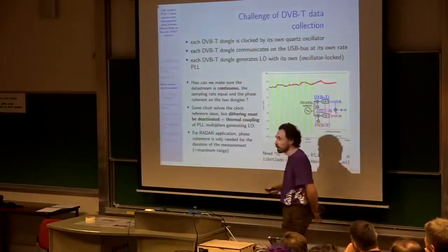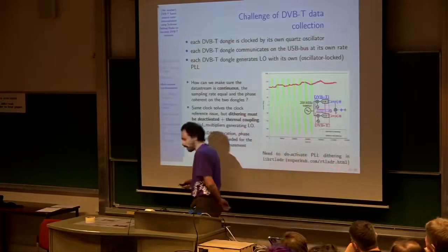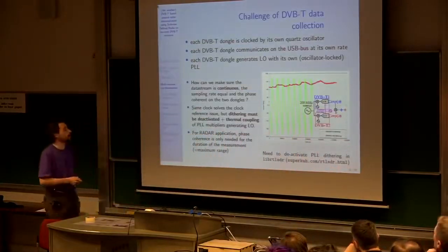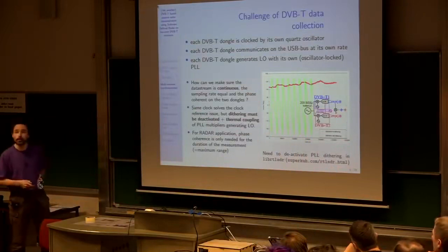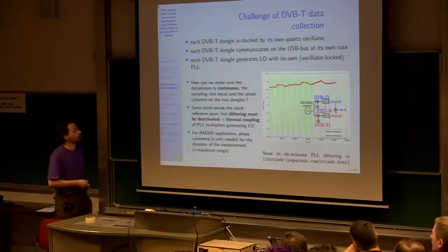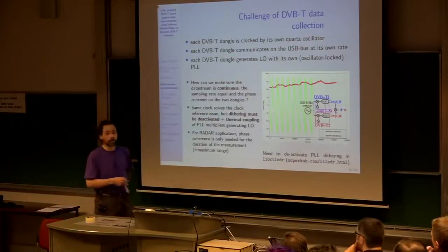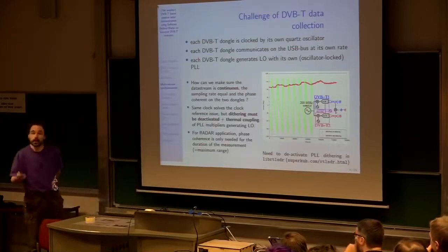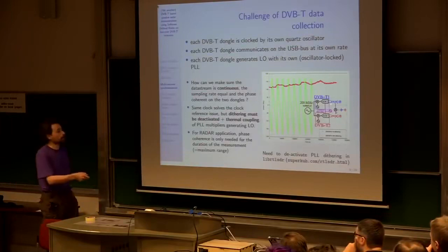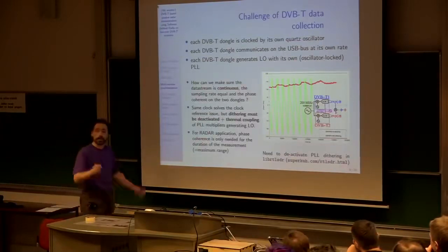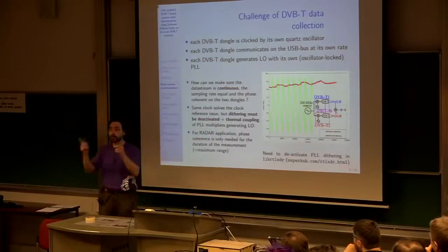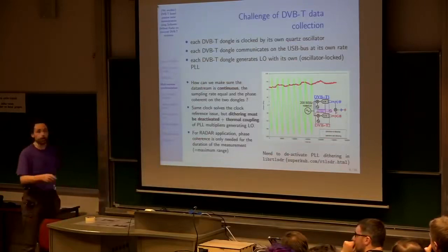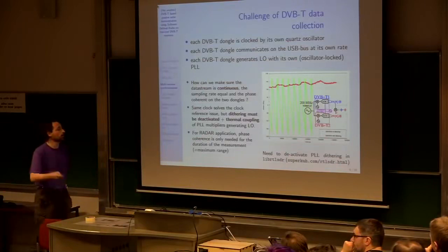Now, the first thing is frequency synchronism. The fractional PLL inside the DVB-T actually uses dithering to have high resolution, so sub-400 Hertz tuning resolution. I cannot explain why, but my understanding is that because the dithering of the two local oscillators is not triggered at the same time, the pseudo-random generator is not running synchronously on the two DVB-T because they get their orders on the USB bus at different times.